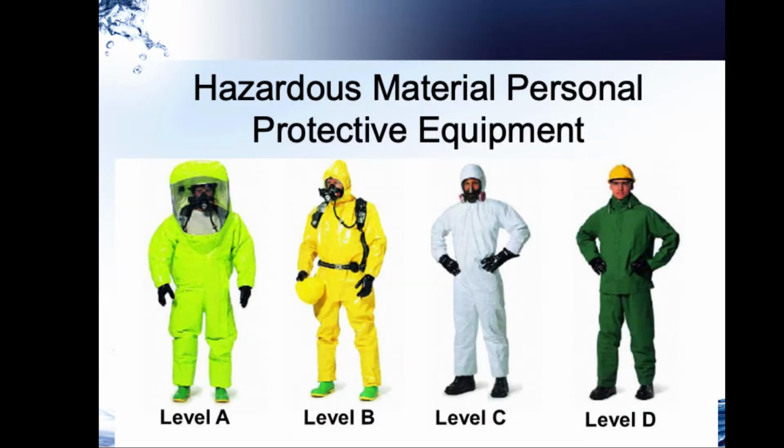So we're going to move past the first responder, just awareness level, because at that level you don't wear any personal protective equipment. And we're going to start to take a look at the different levels, A, B, C, and D. And you really can talk this whole thing through the slide, because what differentiates A from B? Besides the completely encapsulating suit, which means either we do not know what the agent is, we can't measure its concentration, or it can hurt us through absorption, the difference is just the suit itself. Both of A and B are in supplied air.